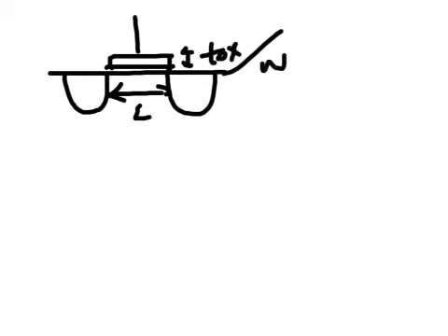So as a result of advances in fabrication technology in the last 20 years, the transistor length, the oxide thickness, as well as the width of the MOSFETs, have been decreasing. The reason for decreasing these geometrical dimensions, known as transistor scaling, is so that one could get significantly faster transistors that operate at lower power for free. Just by reducing the size of the W, the L, and the TOX, the transistors would operate faster and consume less energy at the same time.